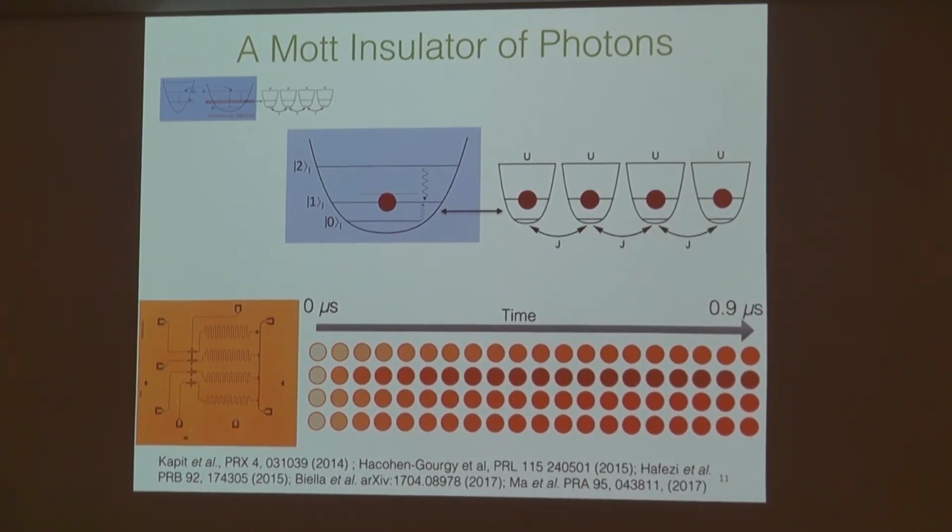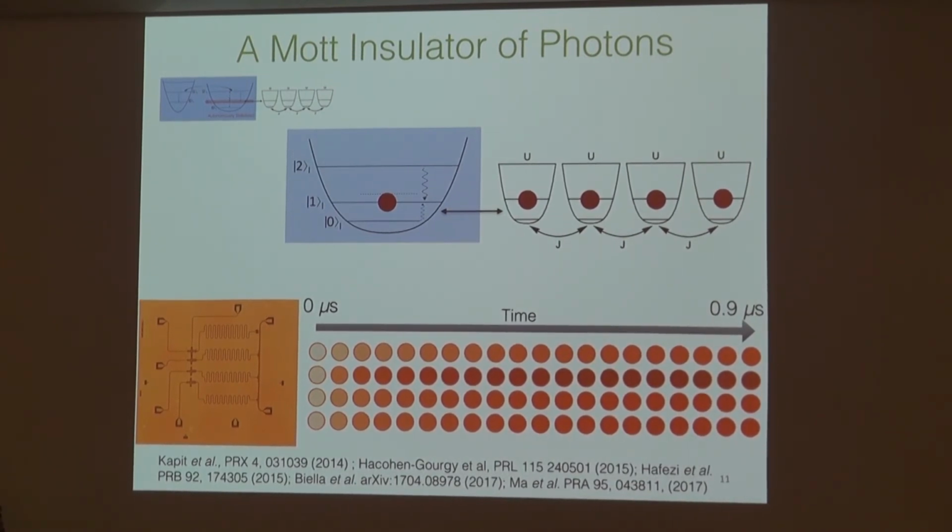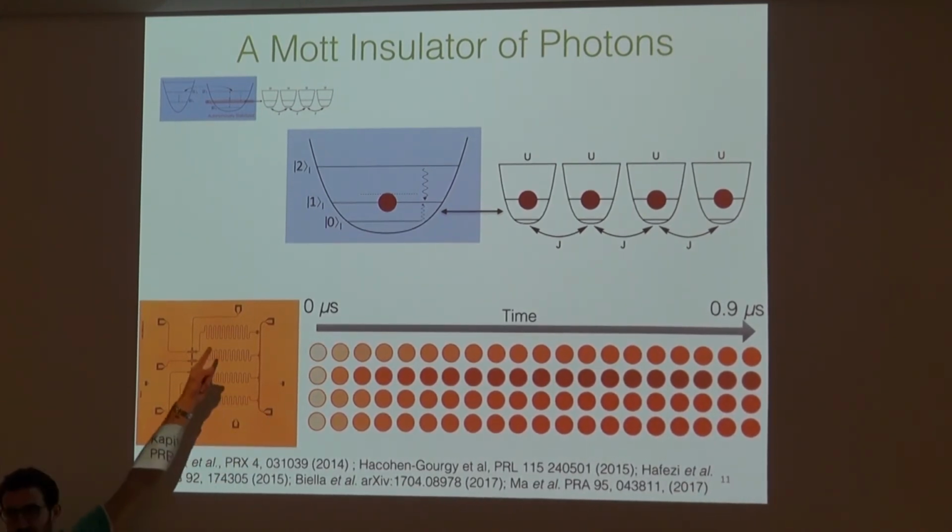Is that like a blob of oxygen deposited by a student that's about material? No, I mean, I think the point is the Q of this resonator is determined by the capacitive coupling to this 50 ohm transmission line. So this guy is just more strongly coupled. Okay, but not so bad that you can't measure it. Yes, exactly.